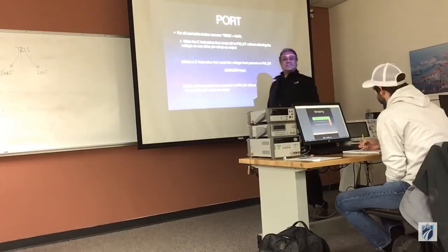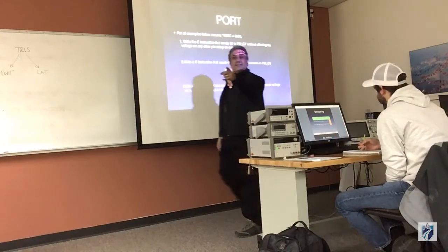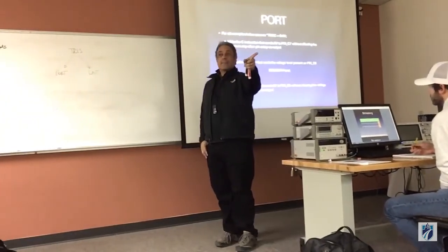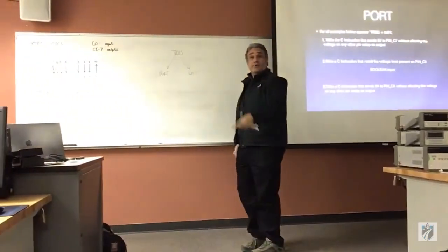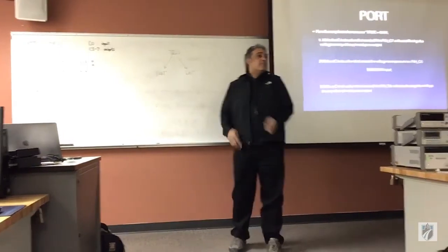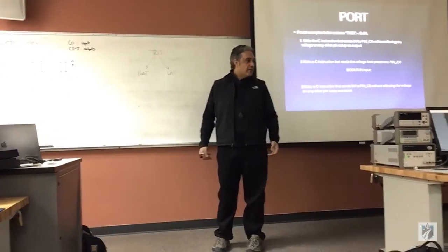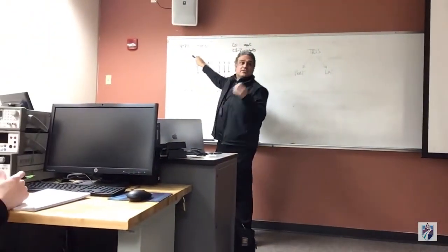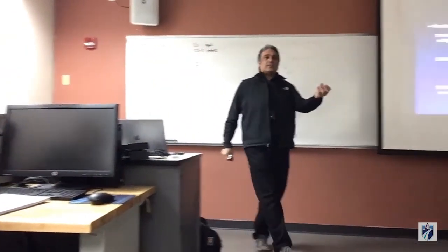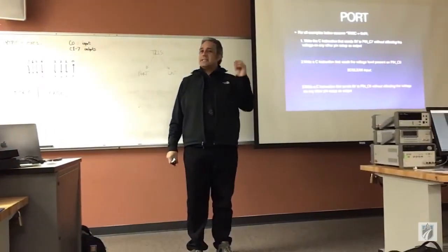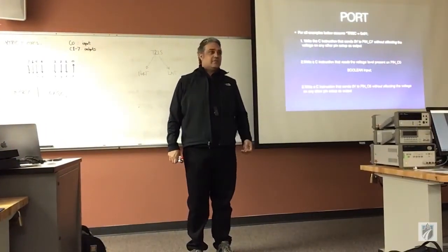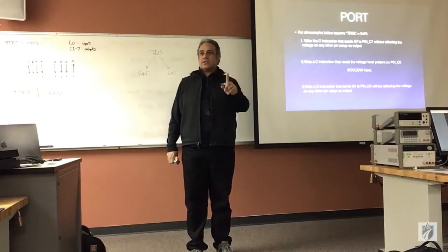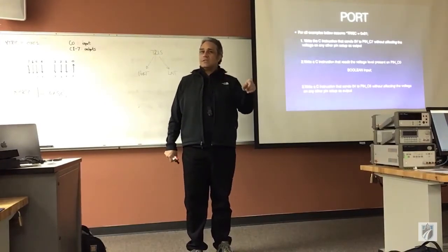Is there an instruction? No. Why not? Because it's not set up as an input. Whatever instruction I give you will not work. Why? Because my setup is not conducive to an input on C1. It was set up as an output. So I can't read on C1. See? It's a trick question based on the knowledge of circuitry.